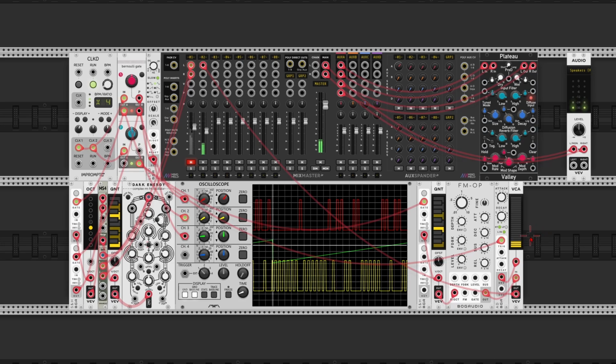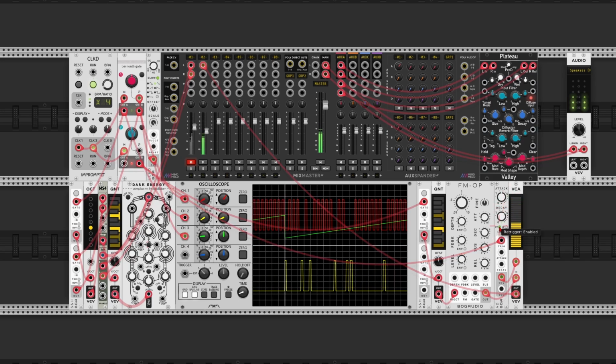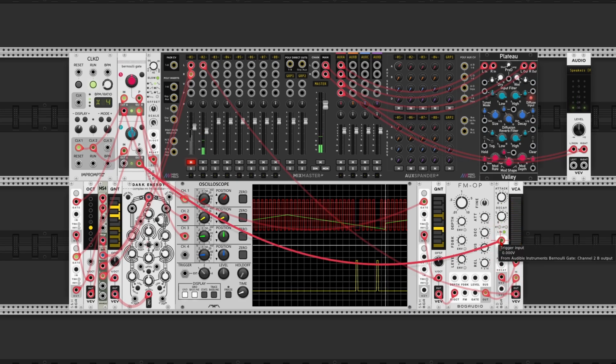But I want single long notes to play. And you can hear that they change when a trigger is received, and the volume envelope also gets re-triggered. On the AD module we can fix this easily. Disable the re-trigger, and as long as there is an envelope still active, incoming triggers will not cause it to increase again until it is finished.